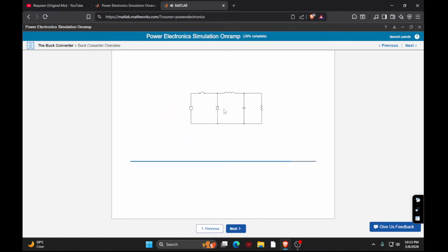Simulink and Simscape make building these systems simple by providing blocks that model each of these circuit elements. In particular, the switching and filter elements together are available as a single block. In the next activity, you'll explore this block and its parameters, and learn how to model a buck converter circuit from scratch.